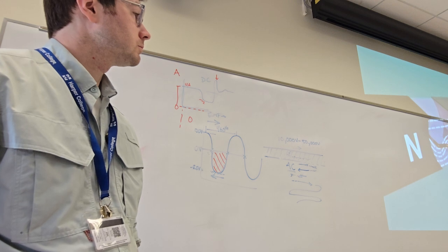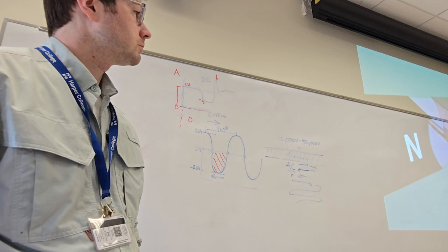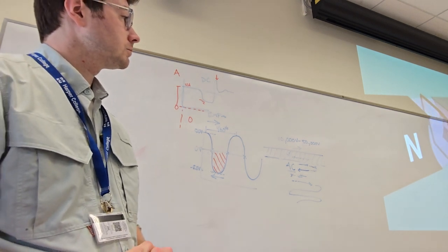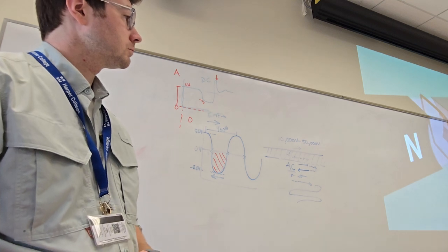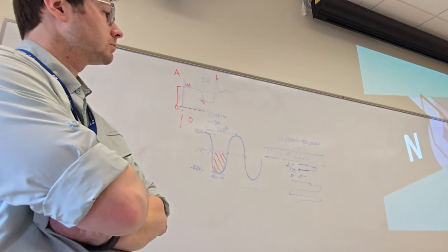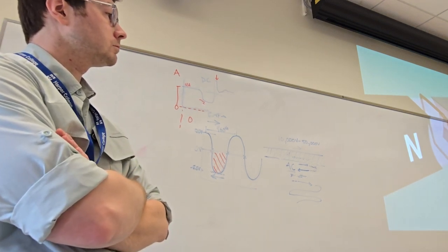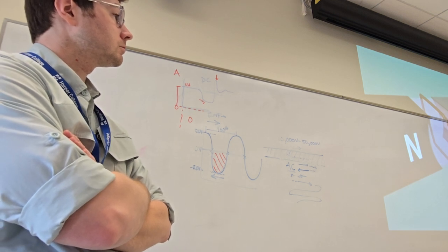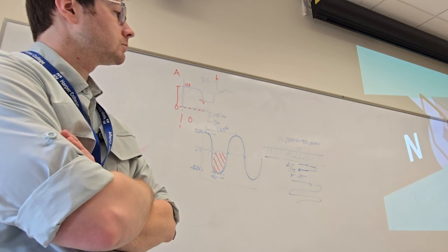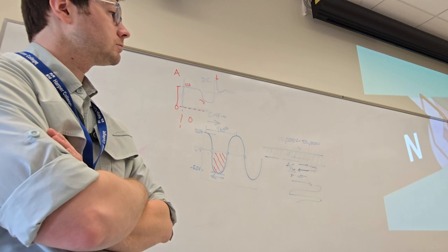This forces one side of the loop up and the other side of the loop down. The motor effect causes the loop to rotate until it is at 90 degrees to the magnetic field. To continue rotation, the direction of current flow in the conductor must be reversed at this static neutral point. A commutator is used for this purpose. In this example, the commutator consists of two semicircular segments which are connected to the two ends of the loop and are insulated from each other.